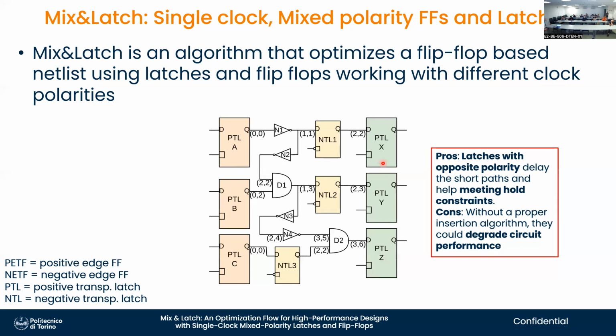Okay, so this is not as flexible. It is much less expensive because, instead of putting a negative latch here, we could put a couple of inverters or 4 inverters that would slow down the signal, and they could be tuned much more finely. The problem is that they cause area increase. And as I said earlier, you don't want to increase the area of your circuit too much. So we will see that we want to limit the amount of area increase to something that is more or less linearly dependent with the increasing performance, because this is something people are already used to.